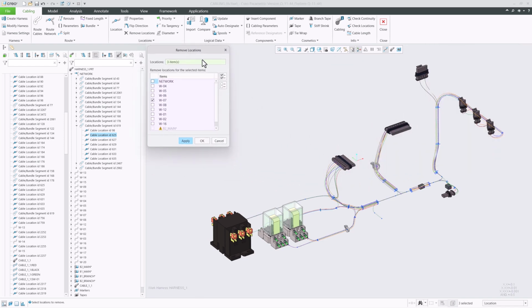Previously, Creo simply blocked invalid selection instead of filtering them out, which required more precise selection and took more time. As you can see, feedback was also improved. The preview is now fully dynamic. This means it will show you the result of the operation following any change in the dialog. Additionally, hovering over the wires in the dialog will highlight them in the graphics for easier identification.